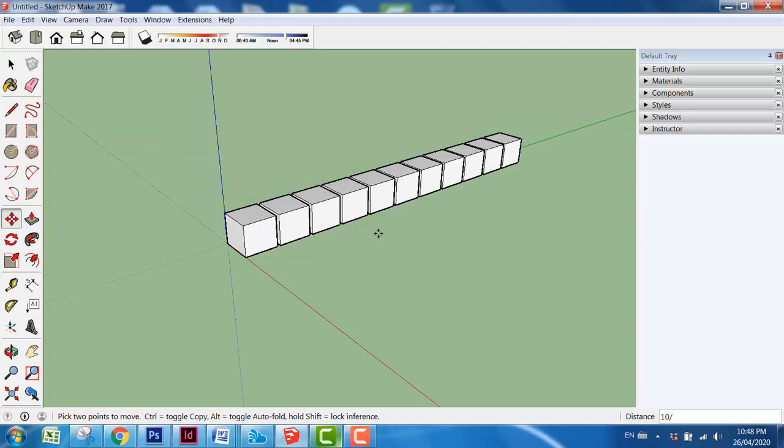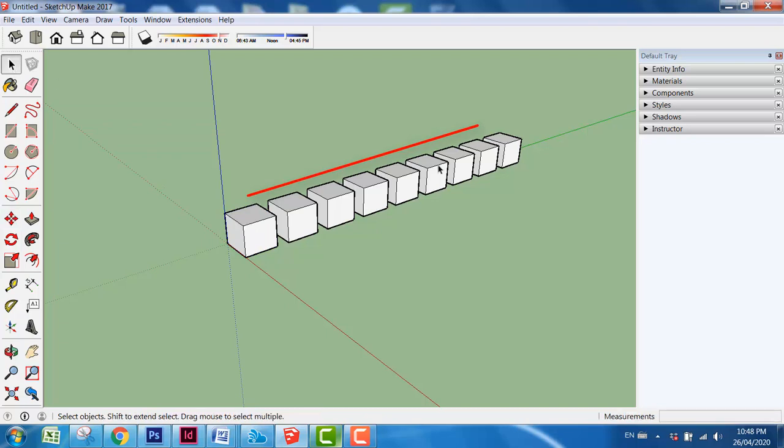So I made a copy from the first object, I put it at the end, and then typed the number with slash. And because we are still inside that command, I can change it. So what about 4 slash enter, 6 slash enter, 8 slash enter. You see it's exactly inside that limited area that we defined here.